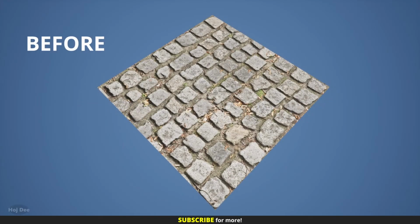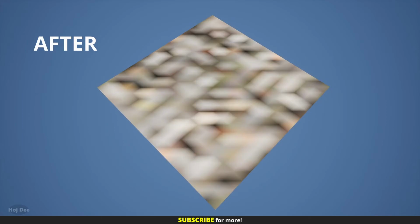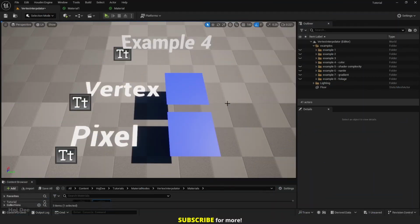We shouldn't use this node with textures that have per pixel data. It removes the details. We can use it in places where we know the value between vertices is going to be linear, or places that don't need per pixel details and all the changes are gonna occur per vertex, like solid colors. For example, here the material doesn't have any per pixel detail, so using the Vertex Interpolator node optimizes the material and doesn't affect its visual fidelity.